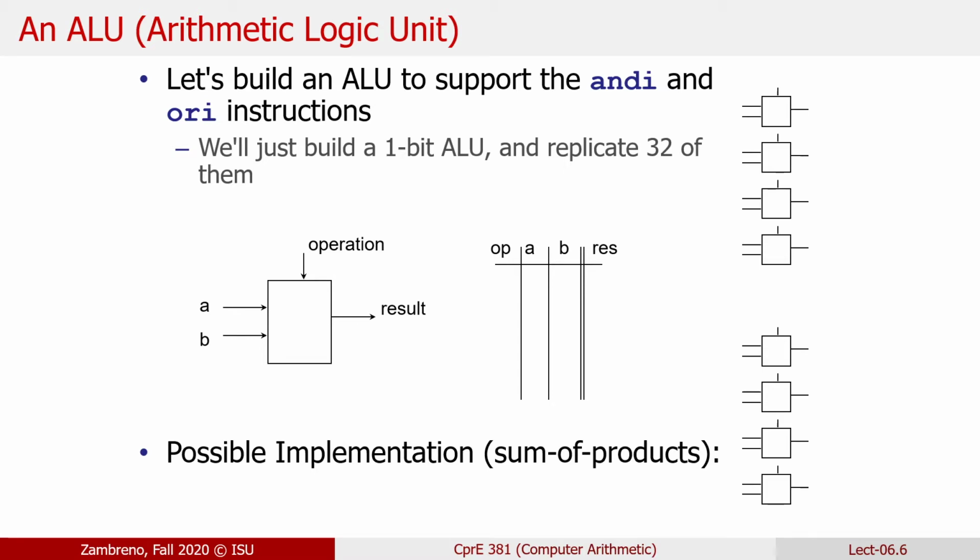And there is no necessarily right way. There's different design considerations that we have to trade off. There's the consideration of, well, how many lines of source code is it going to be in my VHDL when I do this design? The implication being that more lines of source code means it's more likely there's going to be a bug, right? The more lines you write, the more likely you're going to have a mistake somewhere in your code. We don't have, I believe, a good enough intuition collectively as a class to be able to truly say that this implementation strategy is going to be better than another from a hardware gates realization perspective or from a critical path perspective.